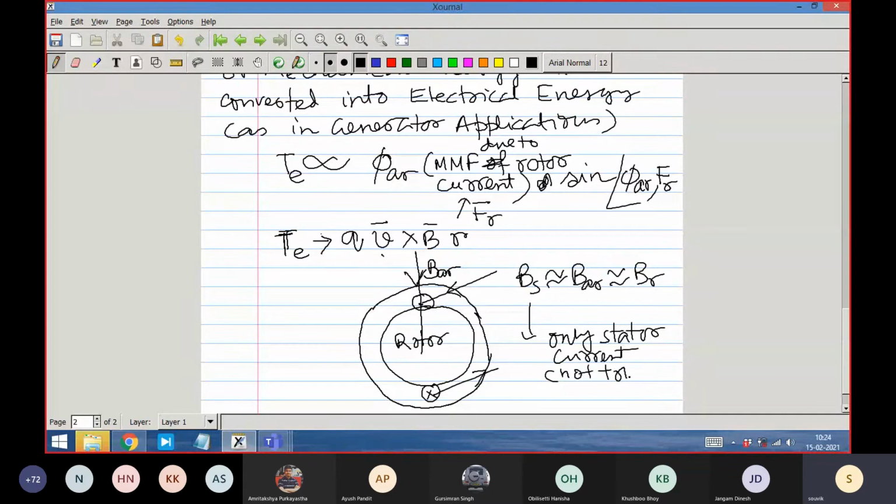You know why? Because a coil, think about a coil, very ordinarily. What is its flux linkage? This linkage is due to the current that is passing through it. But if any other coil is magnetically coupled, that is also producing flux. And this flux path, though it is not created by current in its own coil, is linked by this coil. So rotor current created flux lines are also linking this, because everybody has a confined, defined path.